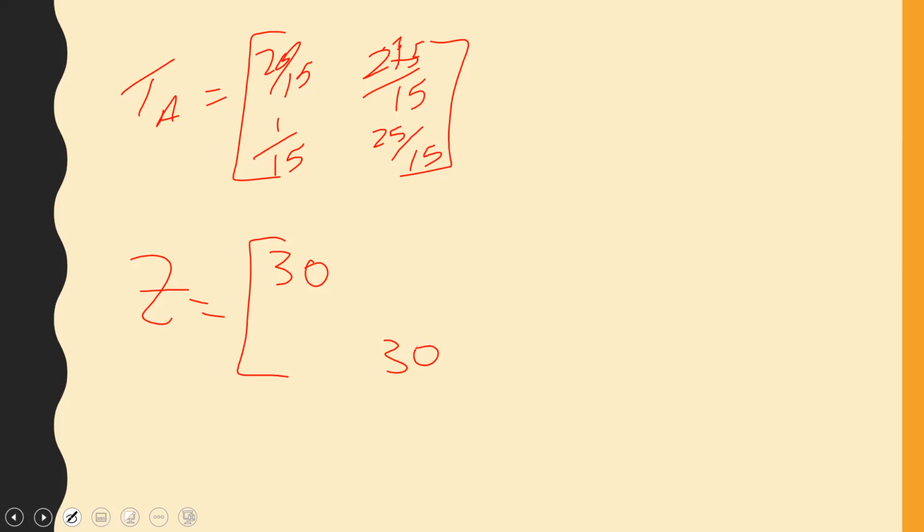You're flowing through the 20 ohm resistor, yes? Yes, sir. Good. So what's V2? V2 will be 20 I1. Agreed? Yes, sir. So what is Z21? 20, sir. So if Z21 is 20, then Z12 is 20.